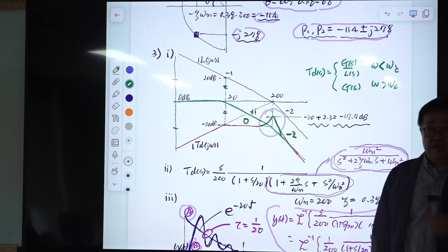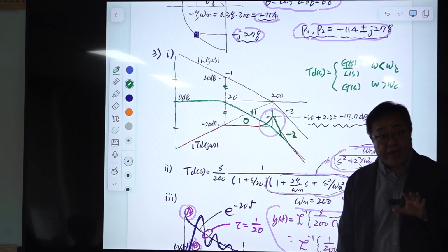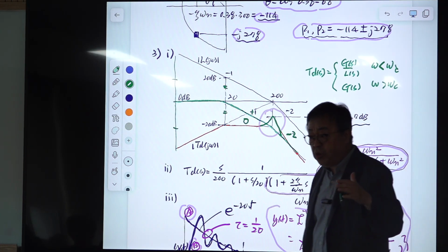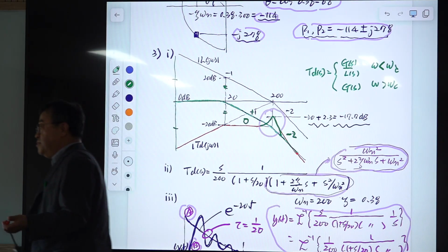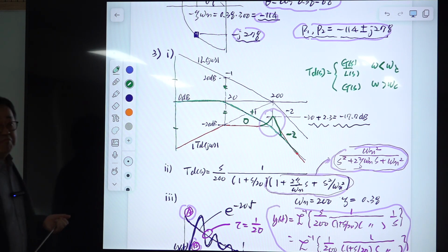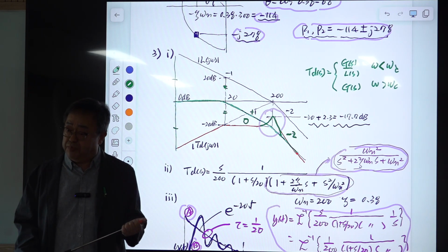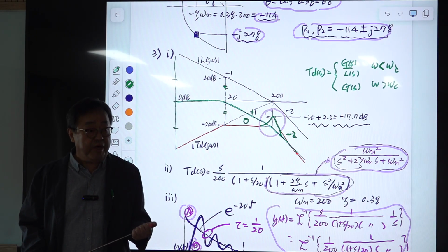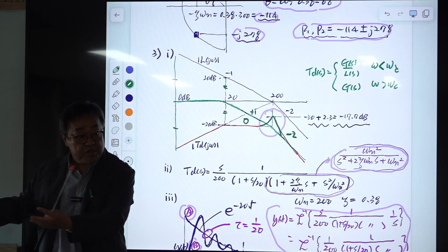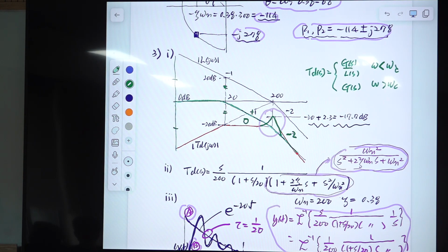Oscillation is regulated by the law, right? So this will be a source of EMI or something. So maybe you think that this is okay, my system is still working, but you cannot make it a commercial product because of the EMI regulation. Then you need to kill all this unnecessary oscillation by proper damping. Okay, for that you should know the source of the problem first.